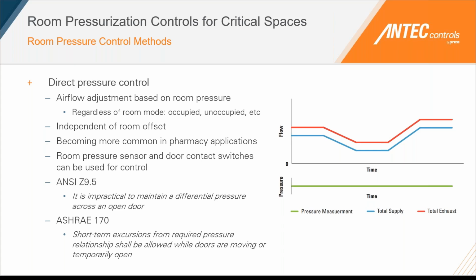ANSI Z9.5 states that it is impractical to maintain your differential pressure while that door is open. And ASHRAE 170 also states that short-term excursions from the required room pressure relationship shall be allowed while the doors are moving open and closed.